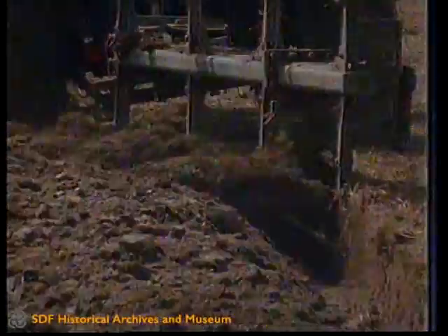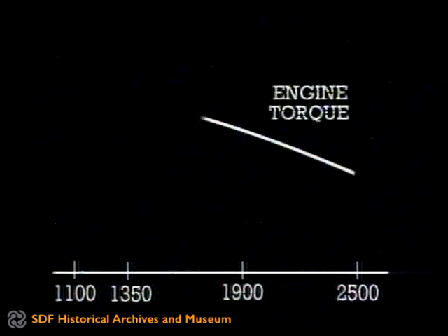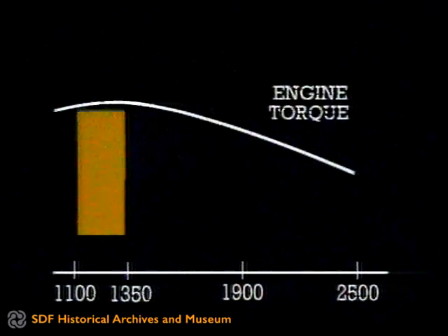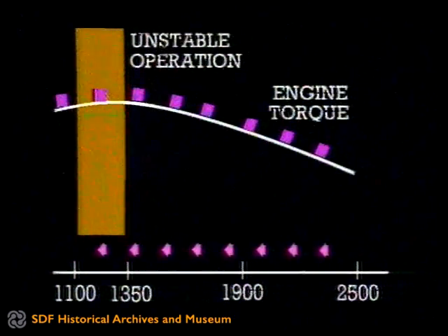On the graph of the 1004 engine, from observing the torque curve, it will be seen that on reducing the RPM down to 1,350 RPM, the torque increases, and the engine is able to withstand even greater loads. Also shown on the same graph is the zone in which functioning becomes unstable, because the torque, instead of increasing, decreases as the RPM decrease. At every overload which causes the RPM to decrease down to the unstable running speed, the driver is forced to change down in order to return the engine to a stable running speed.